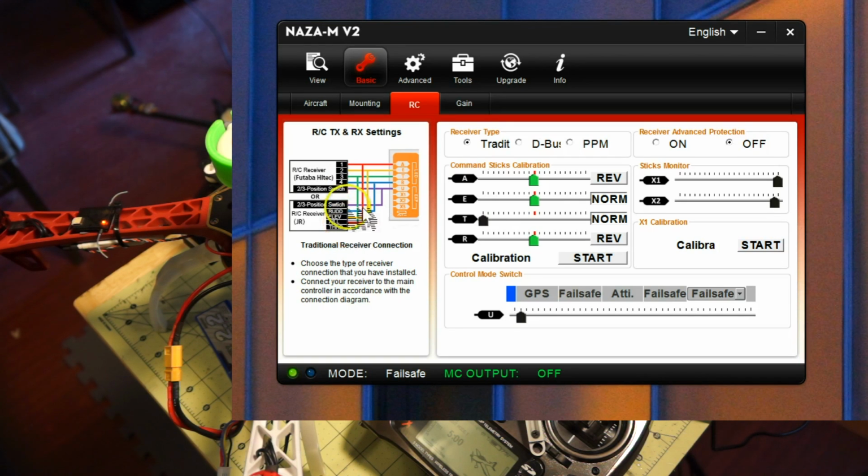With this particular Spektrum, we have them listed: throttle, aileron, elevator, etc. And one thing to note with Spektrum is that channel 1 is throttle, whereas this is set up for typically a Futaba receiver, and channel 1 would be aileron. So you need to make sure to take that throttle and put it into channel 3, and your normal with Spektrum channel 2, which will be aileron, into channel 1.